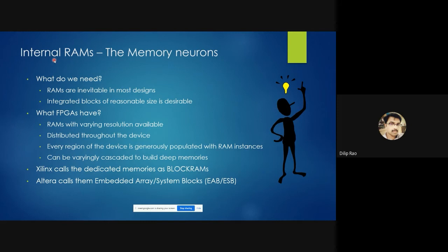For example, there are two main categories of memories: volatile memories and non-volatile memories. The volatile memories can be RAM, the very base. It can be SRAM. Non-volatile memories can be either ROM, which will hold the boot ROM code in a system, or flash, which is going to hold the next higher level of software, which is firmware or middleware. So these are the different types of memories which go to build a system.